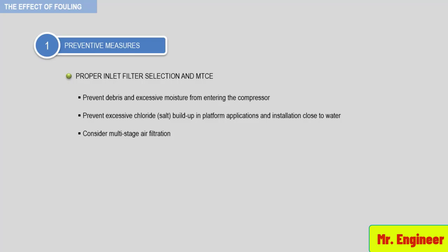Another important consideration is filter maintainability. For crucial services, filters with online cleaning capability should be considered. Be aware, though, that in recent years, pulse-type filters that use a reverse air pulse to clean filter cartridges when filter pressure drop becomes excessive have become quite popular in the industry.